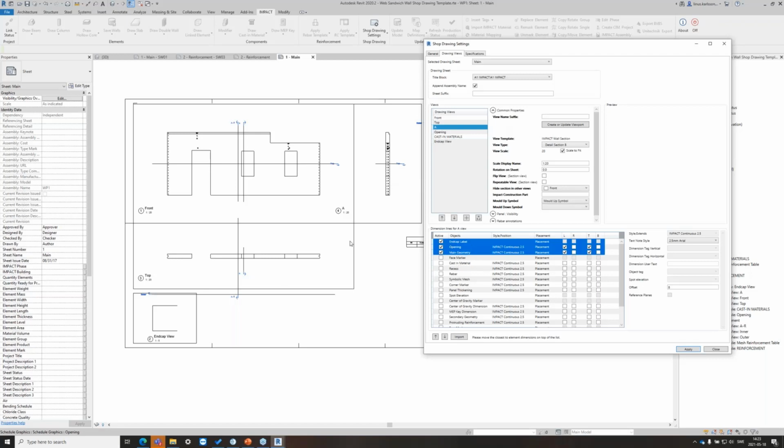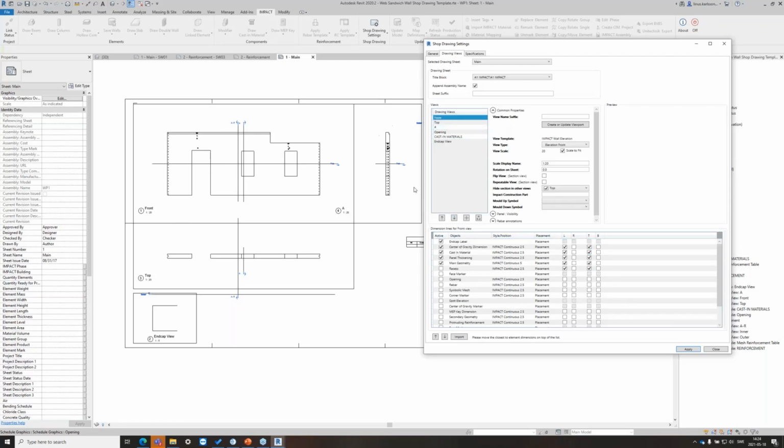And it doesn't mean that I need to have views that are identical like the inner and outer panel of the reinforcement views. It's more that you're probably going to have end cap label on the front view as well. So if I wouldn't have any settings on the front view, I could probably use the view settings that I have for this vertical view and add that to the front as a start. I hope that you get what I mean.